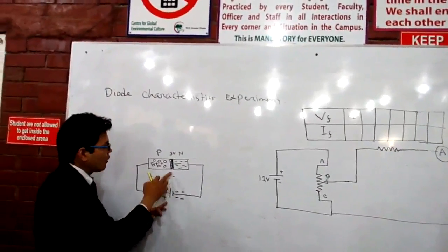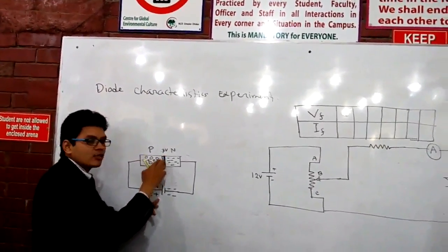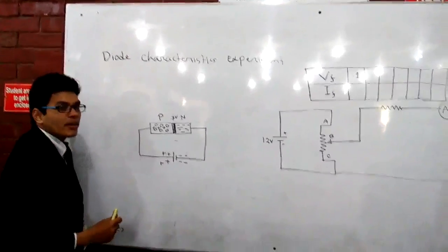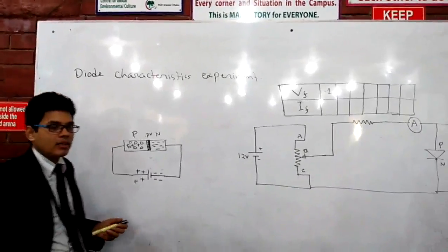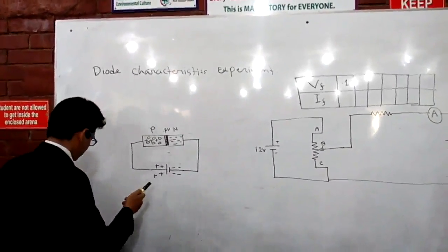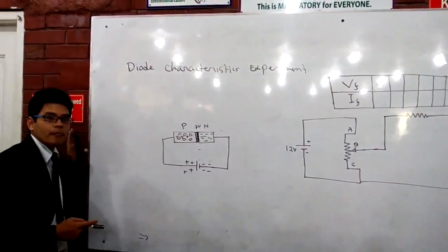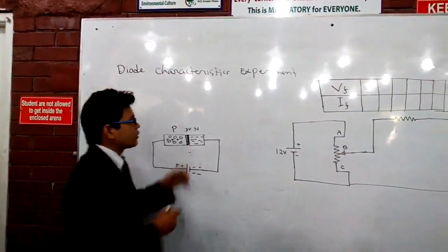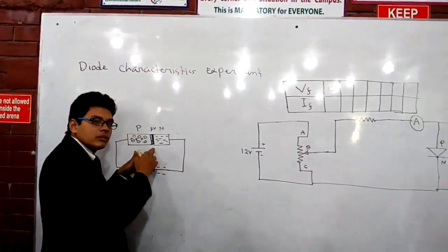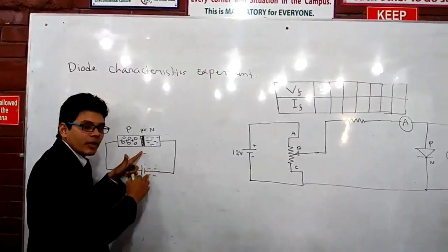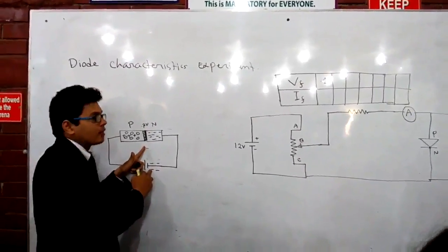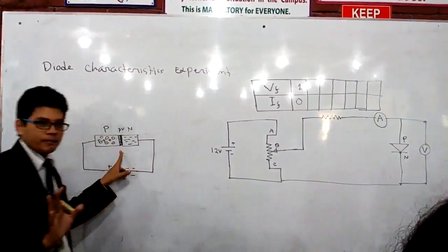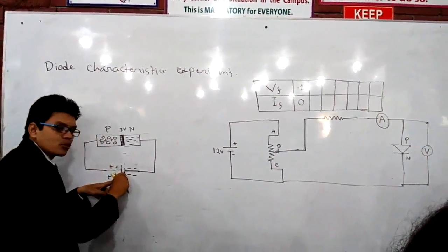At 0.1 volt, what will happen to this? This barrier is too high. This wall is too high, right? Too strong. It requires some force, maybe, right? It requires some more force over there. This doesn't make the wall broken, right? So there will be what? There will be a barrier still at 0.1 volt applied. Got it? Yes, sir. So that means we will have no flow. That means current will be 0. Got it? Yes, sir.